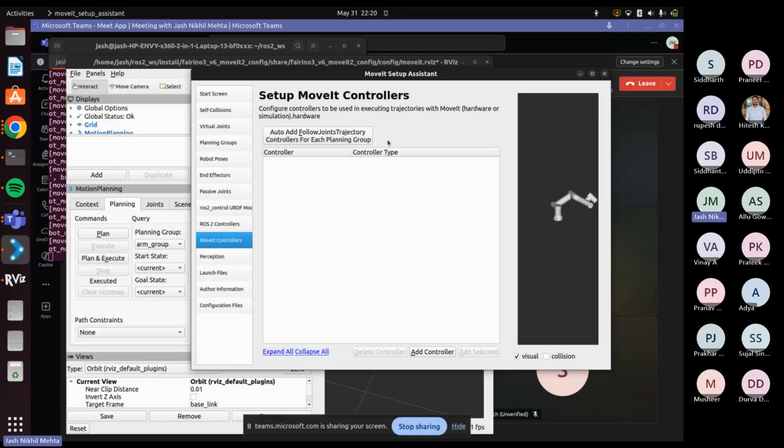So you can make an entire trajectory of how it should follow and where it should stay for a long time. You can load the robotic arm and remove the load. Basically hard coding for now. Then once you introduce perception and AI onto this, you don't need to hard code the trajectory using Excel. Are you getting my point up till now?